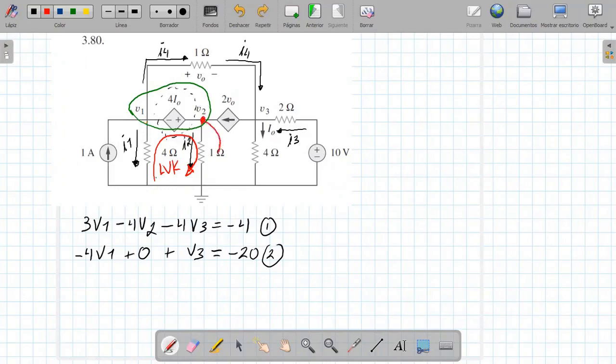V2 is the same. Between this point and ground there is a voltage V2. Therefore I can make a separate circuit. Remember that with more practice you can do it directly, in which I replace this resistor with a source called V1. I say that here it is V1. If I am removing this resistance by its equivalent in voltage, because we know the voltage, here we do not need the resistance.